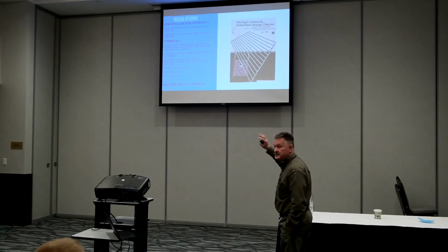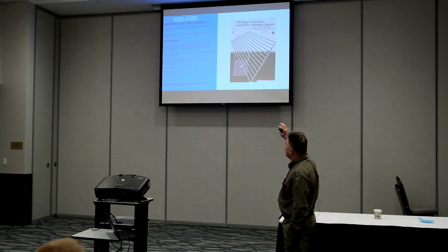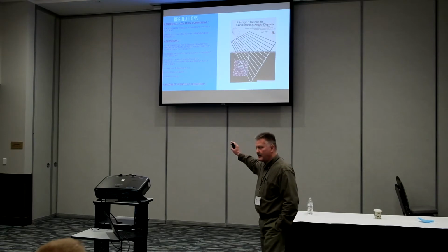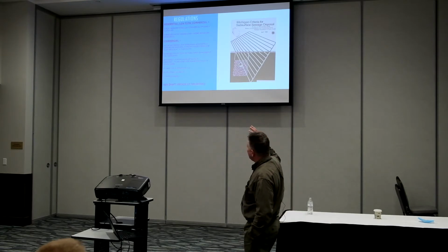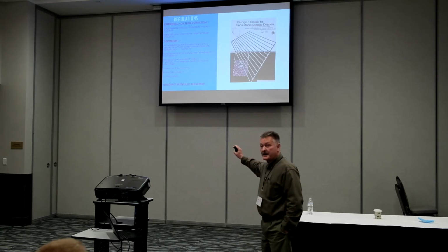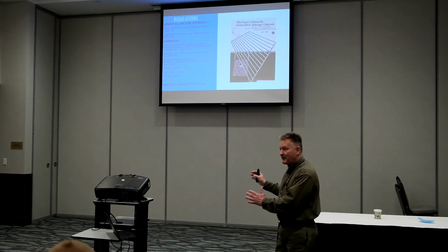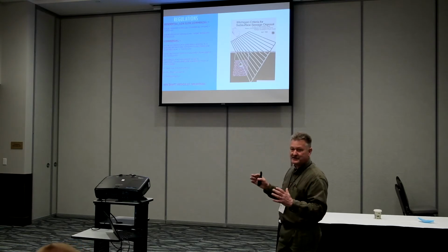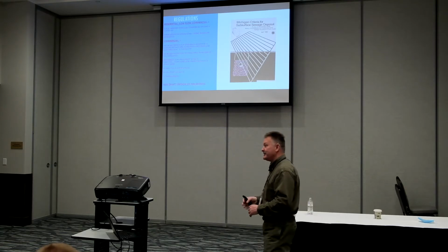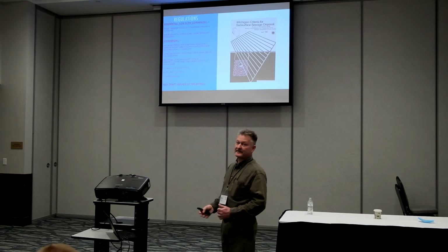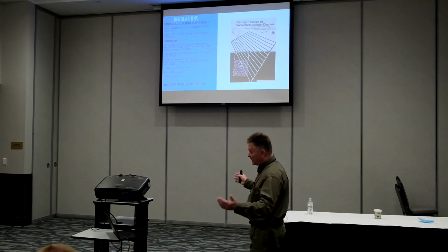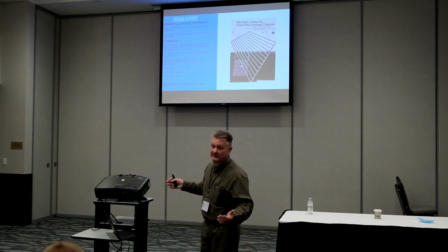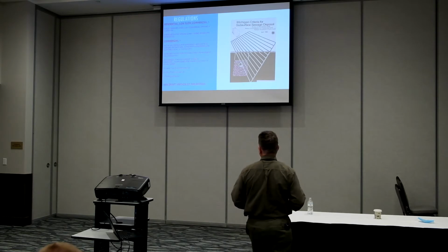However, in commercial applications or Michigan criteria, we're still just dealing with the flow volume and we're sizing based on hydraulics. Now, Michigan criteria does recognize that there is something different about restaurant waste. In one of the appendixes in the back, there's a section that says if we're dealing with a restaurant, you shall have more tankage. You're only limited to sand or loamy sand. It doesn't say why we have to have this concern, other than we observe a higher failure rate in those situations.